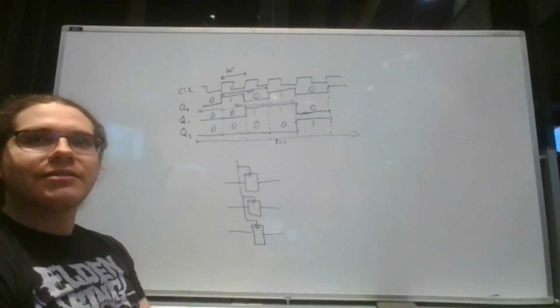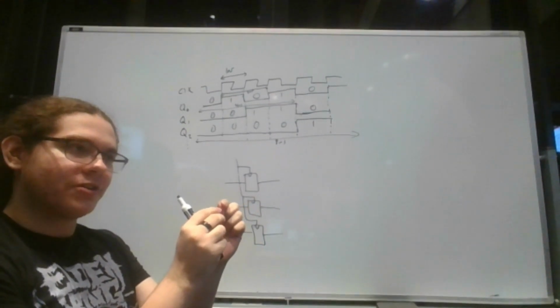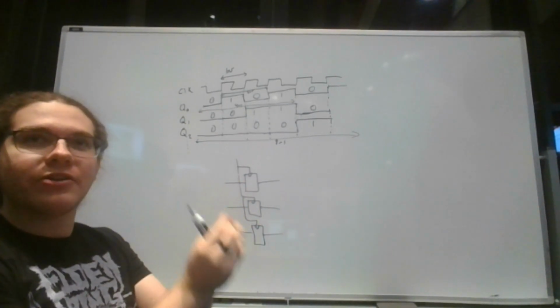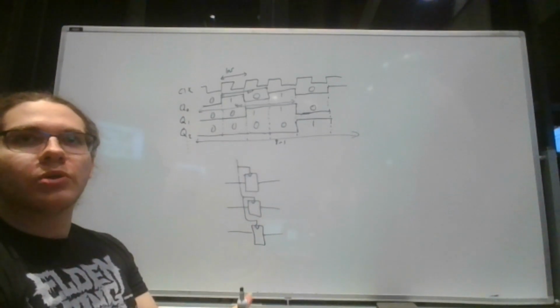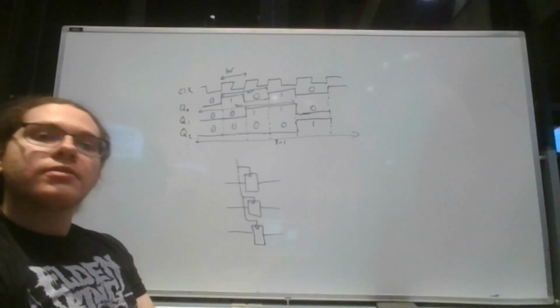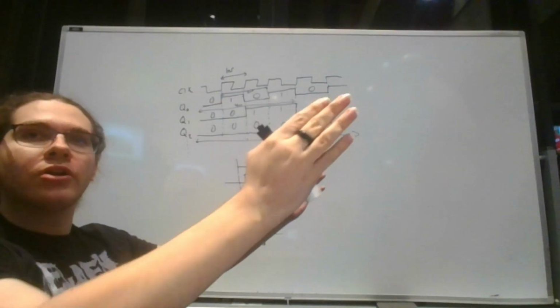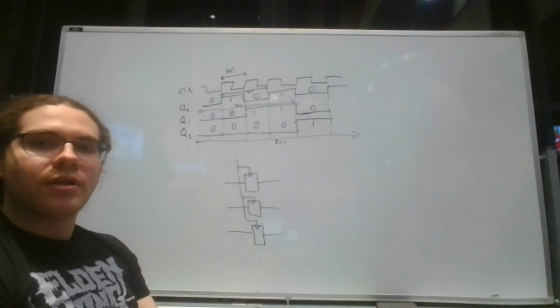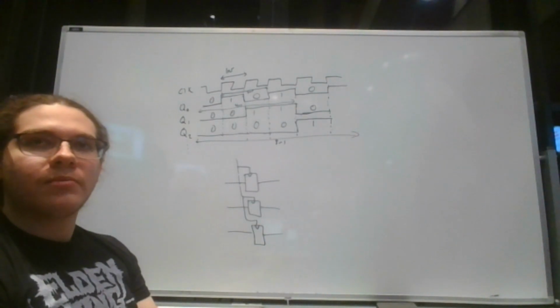Since our technology has gotten so small, those things are nanometers apart, so the signal races through in basically no time at all. That does become a problem if you have stuff clear on the other side of your chip. You have to deal with clock skew all across your chip, and you have to be able to correct that.